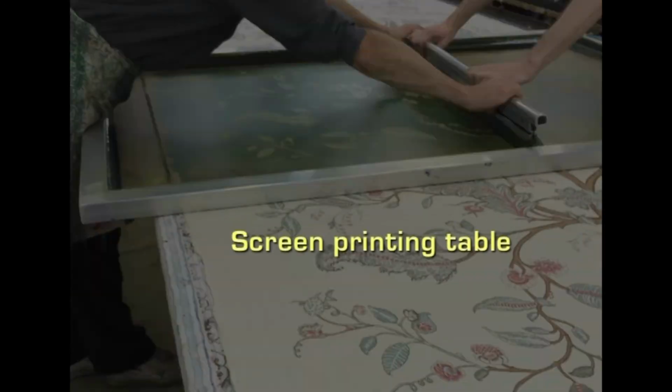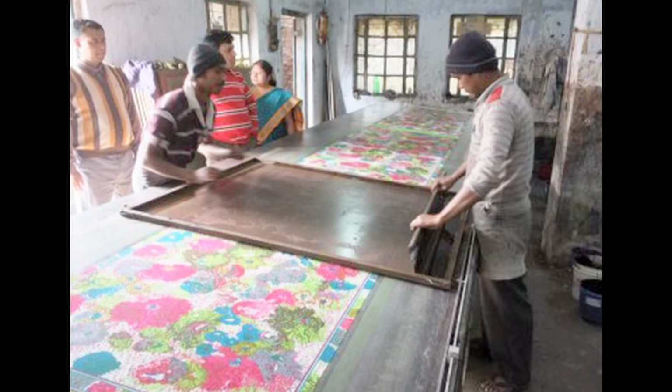Coming to the preparation of the screen printing table, hand screen printing is done commercially on long tables up to 60 yards in length. The fabric to be printed is spread smoothly on the table. The surface of the table is coated with light lac adhesive. The operator then moves the screen frames by hand successively along the whole table.